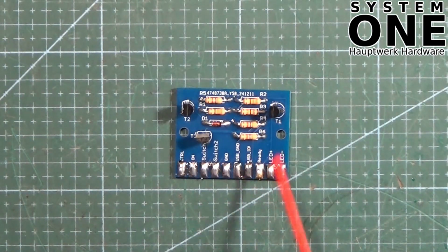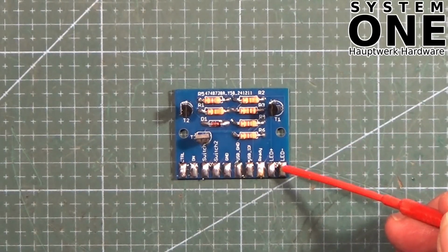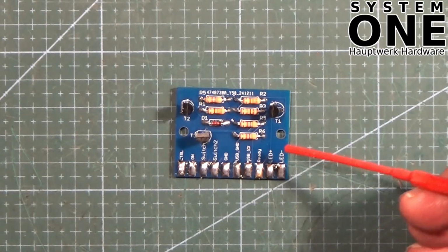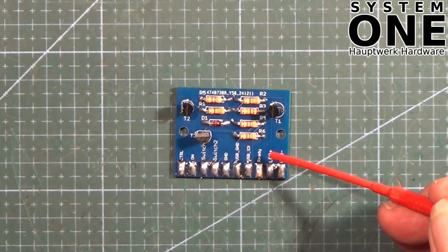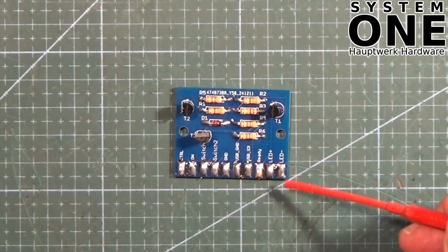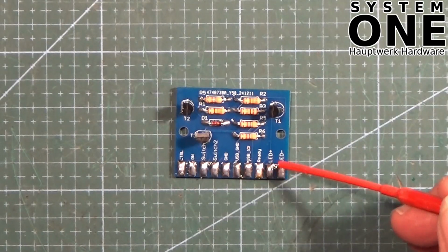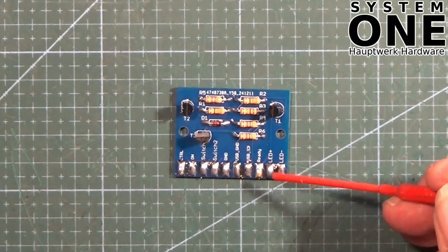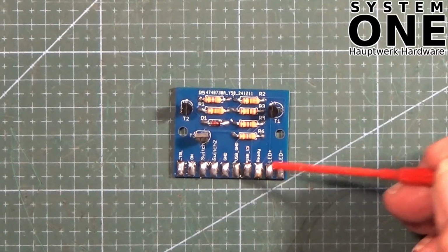Okay, so here's a close-up of our power management board. Basically, it's got the two connections on the right for the LED plus and the LED minus, and the polarity there, the plus and the minus, is for when the LED is red. So the positive lead to the LED going to the plus and the negative lead to the minus, that is the way you need to do it for the LED to be red before it receives the MIDI 100 note on.